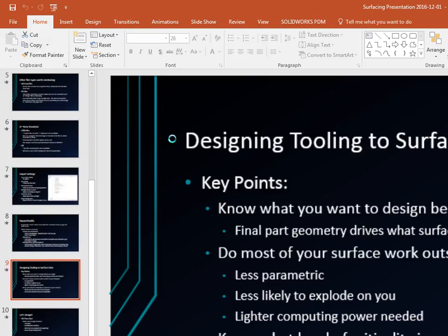You're saying fillet with your surfaces before you extrude up to them or cut? Yes. Oh, okay. That's probably why it's not filleting afterwards like I did. Fillet the surfaces, yes. That's another reason why you would maybe use extrudes versus cuts. Maybe. I use a lot of surface cuts. If you've got surfaces in there, you have to extend them beyond, trim it back, then make it all one body, and then you can put a fillet in. If you've got all nice clean edges and they all meet, I'm just hoping.